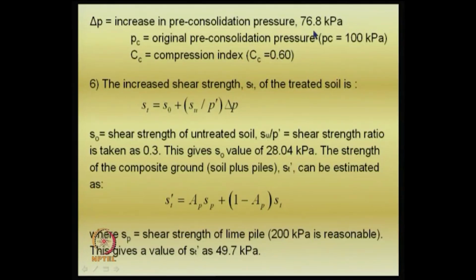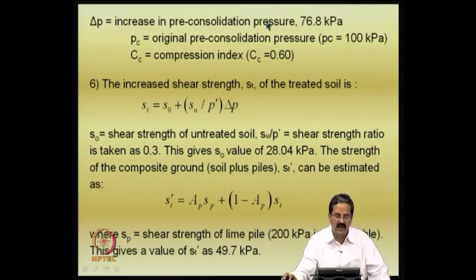I mean the thing is, just by adding lime, I have made an effect of about 75 kPa extra load applied, which you can compare with any other thing. You have surcharge methods and other things, and to apply a surcharge of this, you need 4 meters height of surcharge, and its consolidation is only occurring there. But then here you have chemical changes also, soil is improved and all that, and CC numbers I have calculated.